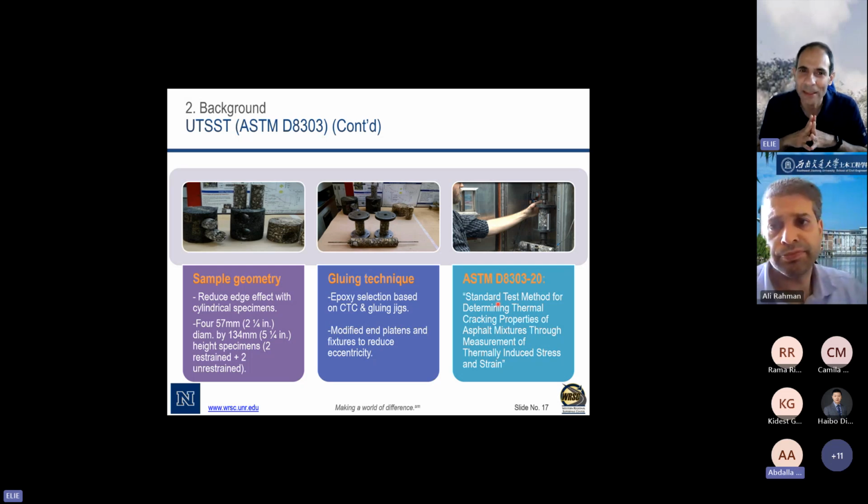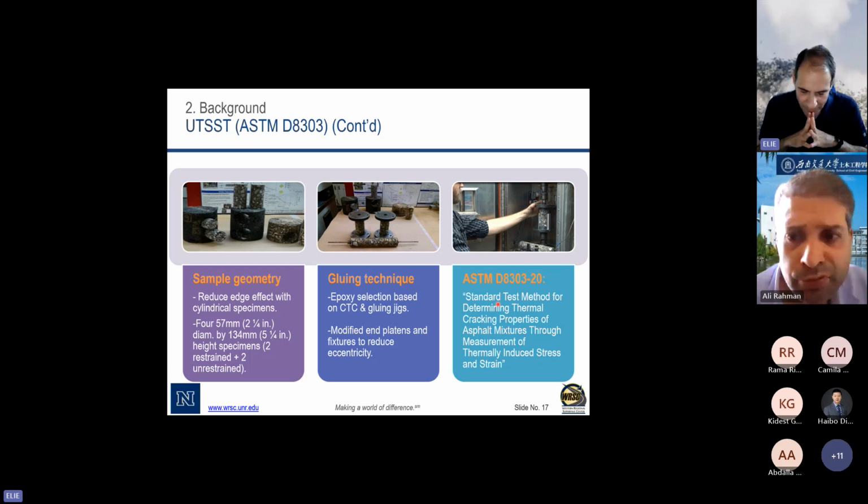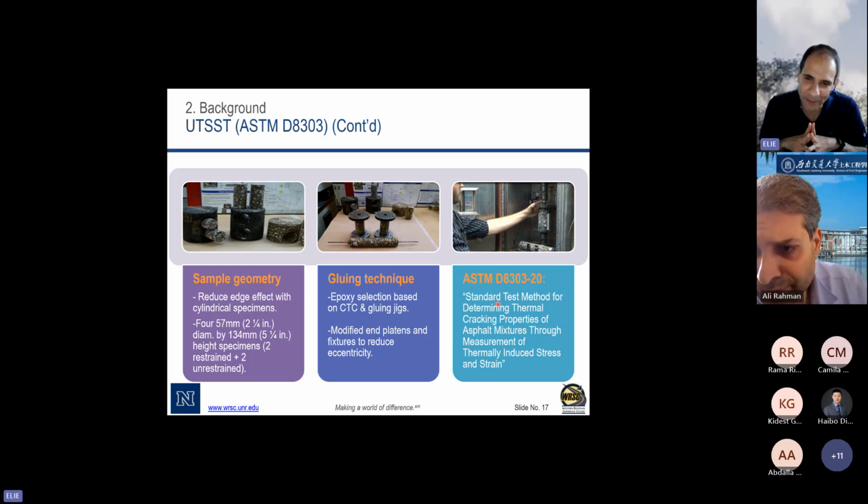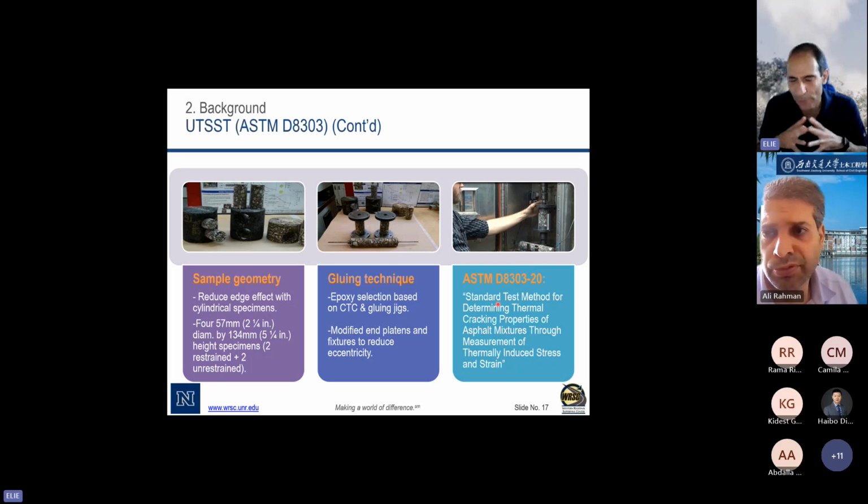Well, I need to caution you because, are you using the nationally calibrated models? Are you using the globally calibrated models that are built into the software? Yes. So that's the first problem: you shouldn't be using those globally calibrated models unless you prove that they are applicable locally.